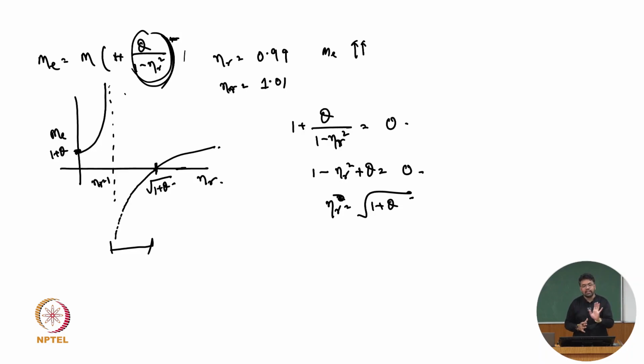It's like we are applying the force in the positive direction, but we see the change in momentum in the negative direction, which, in Newton's law of motion, can only be justified if the inertia or the mass is becoming negative. So that's why this type of metamaterial is famously known as the negative mass metamaterial. Okay.